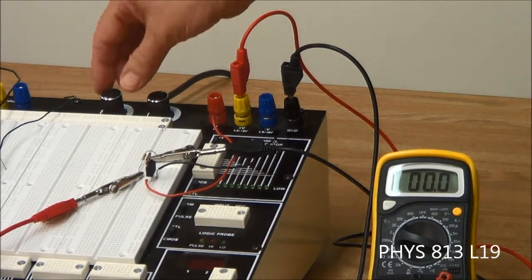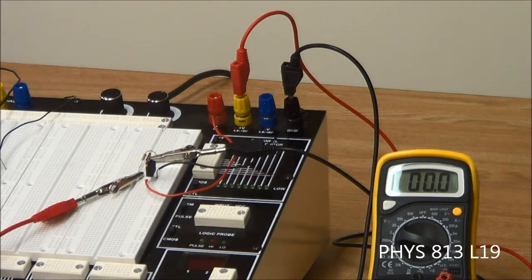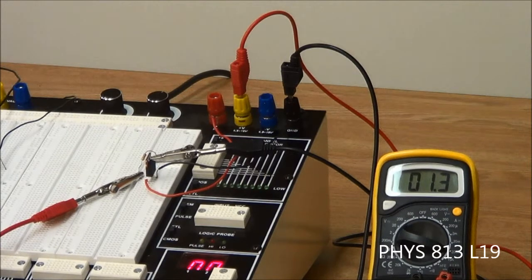Now at this point, it's a good idea to turn this positive voltage control knob down so that you've got low voltage. And at this point you can turn it on, so I'll turn it on. And generally you should notice, do you see any smoke or anything like that? If you do, turn it off immediately. As you go through this, and actually the next circuit, it's a good idea to put your hand over it, and if it feels really hot, then you should turn things off. So far I did that actually with one of the op amps in the next lab, but that means it's not working right.